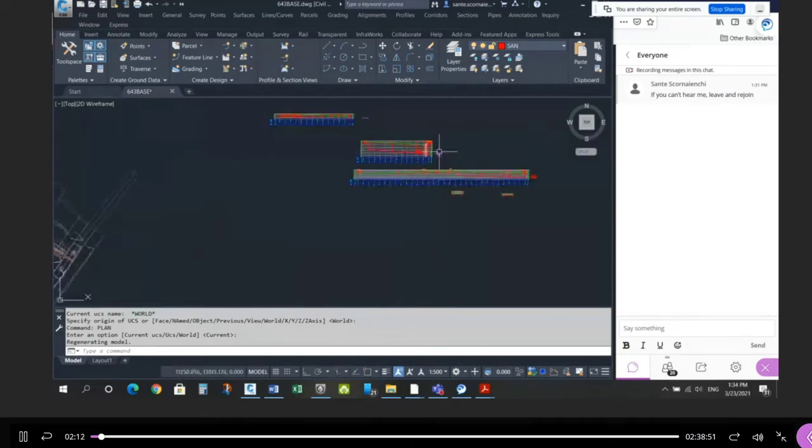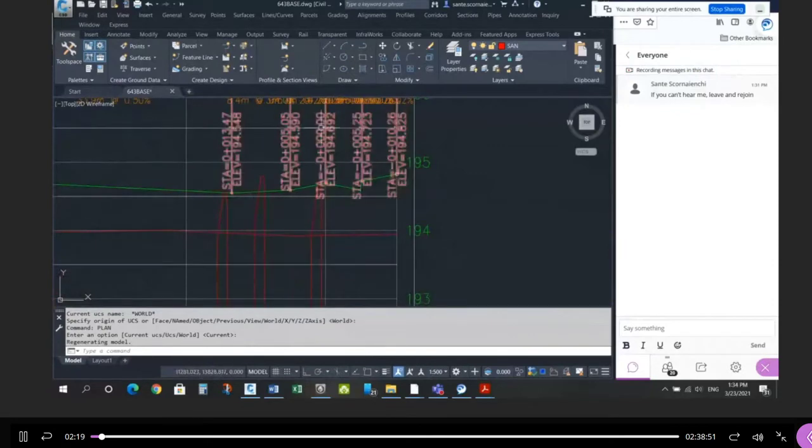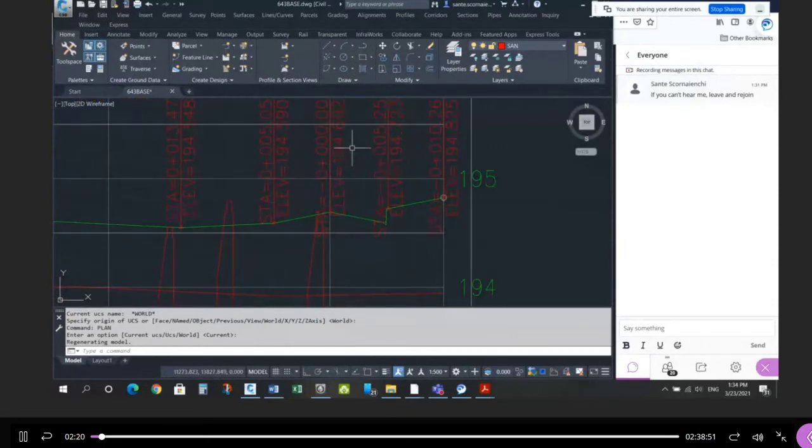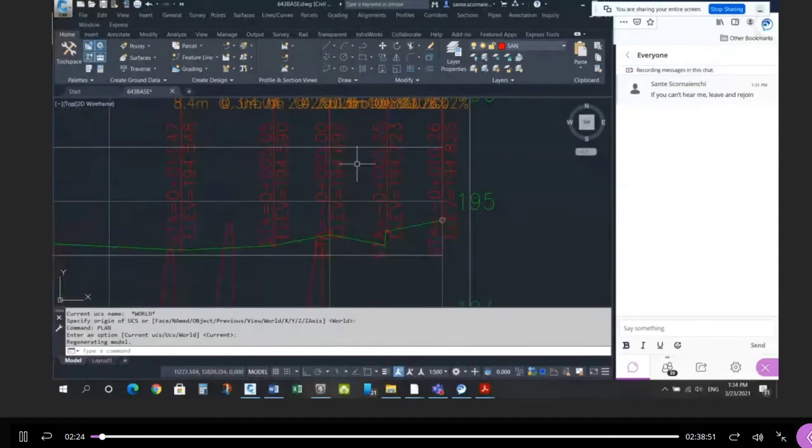When it comes to Street A, I didn't mark Ledger Way. But when it comes to Street A, I was looking for the elevation at the start. So station 0 for Street A should have had an elevation of 194.692. If you were off by a few millimeters, 1 to 2, even 3 or 4 or 5 millimeters, I wasn't too critical about that. But certainly this is the exact elevation of where Street A meets Ledger Way.